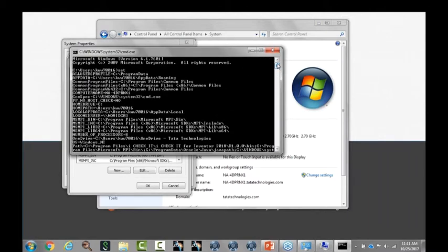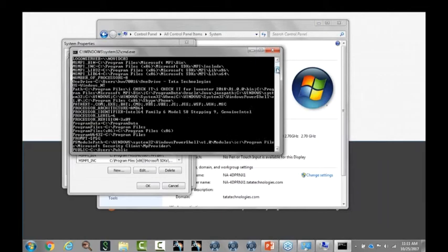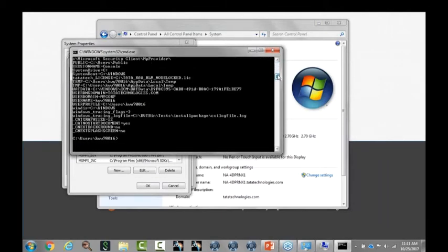If you look closely at these, and you don't need to do that, there's nothing here except for these last 4 that have any indication that it is related to CATIA V5. When you start CATIA V5, the actual executable is cnext.exe, and that will read the environment file and set up a whole bunch of other parameters. In other words, environment variables that are used to say, here's where all the parts and pieces of CATIA are, and those environment variables are then used in the code to go find those pieces.